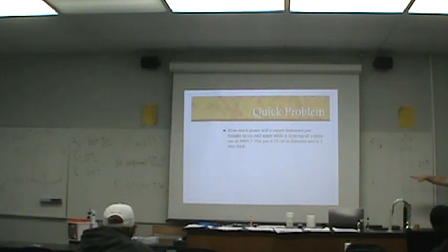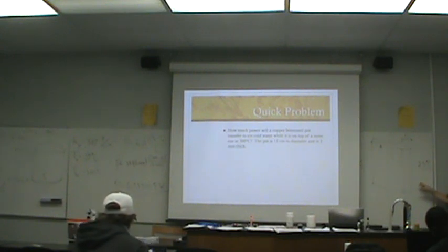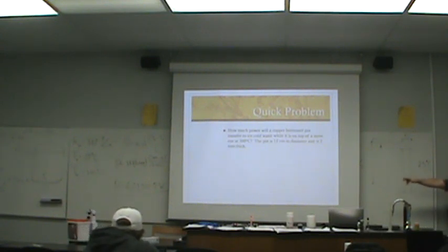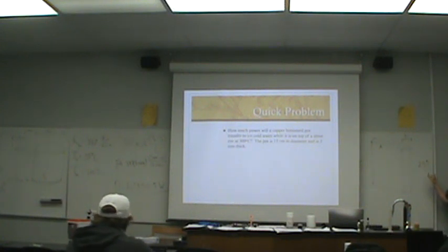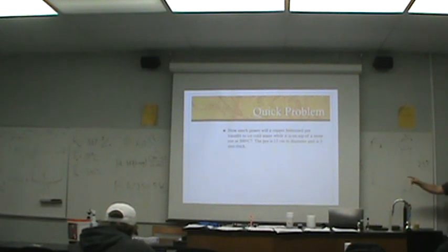And what that number over there can tell you is, say we were looking at the wall of a house, and we got a similar power through the wall of a house. Since that means joules per second, energy per second, and you wanted to keep the inside of your house at the same temperature, you would need to produce through your heater that many joules every single second to counteract the thermal energy leaking through your walls. So again, engineers and architects would need to know that number so that they know what the heater needs to be capable of to keep the building at the right temperature.